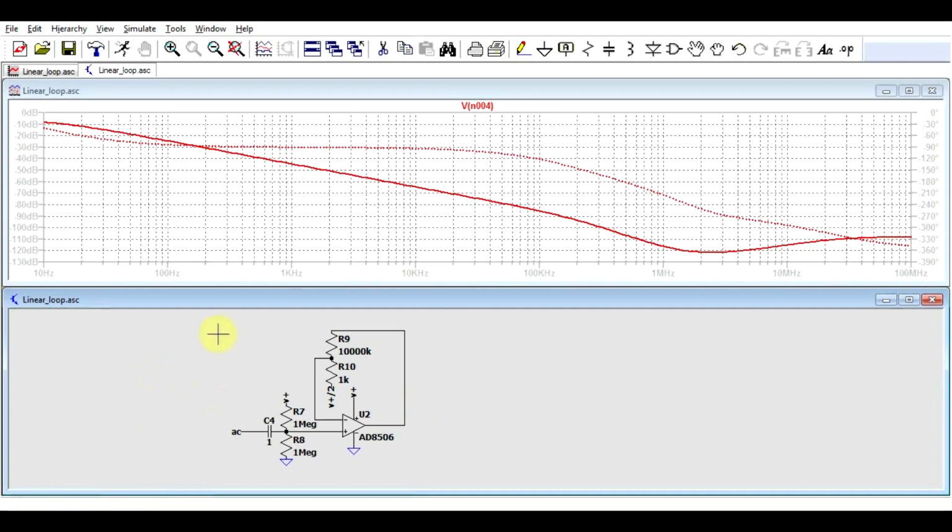First of all, LTspice will calculate the DC operating point of the circuit, meaning that it will consider all capacitors as open circuits, all inductors as short circuits, and then just run a DC simulation to see exactly what are the voltages in the system. After the stable operating point has been obtained, then the reactive components are added and a very small AC signal is injected as requested. Now the problem that we see in this circuit is that we have a problem in the DC operating point analysis.